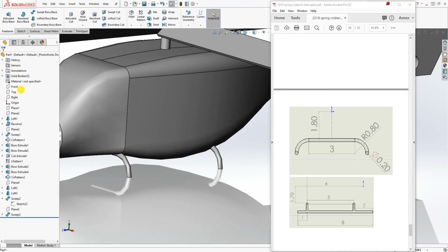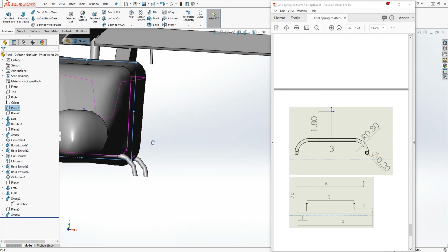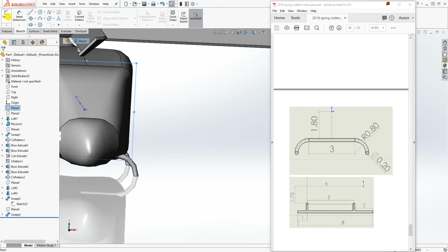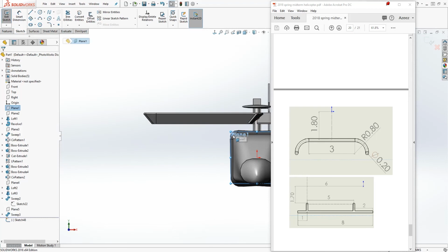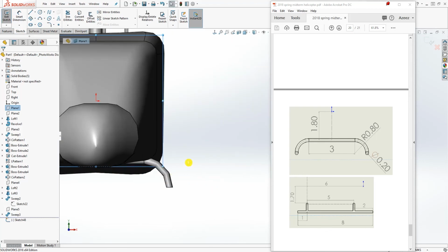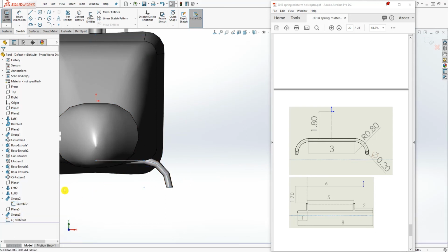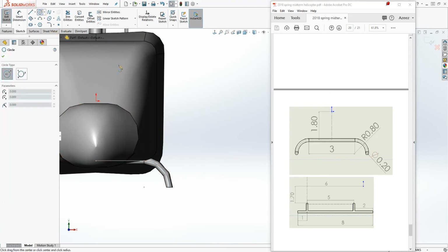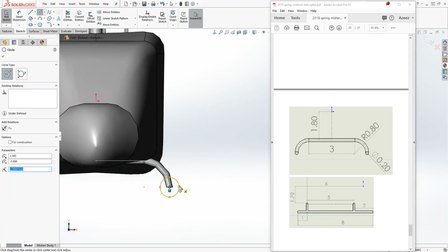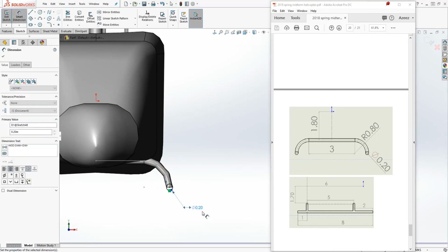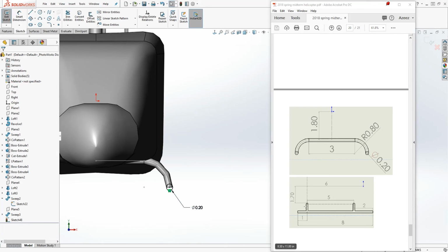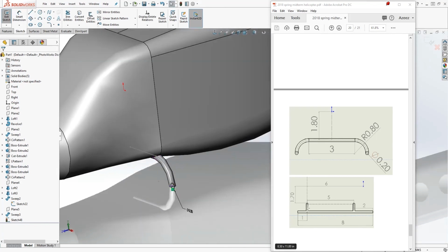So now all we need to do is select the plane 1 again, which is right here, select sketch number 2, and move it somewhere over here, and I'm going to show the sketch of that plane 1. I mean this sweep, I'm going to show the sketch. So while the sketch is shown, I'm just going to draw a circle from this point out, and the dimension for that circle is 0.2, and we are drawing that profile over here. So as you can see, we are drawing it over here.